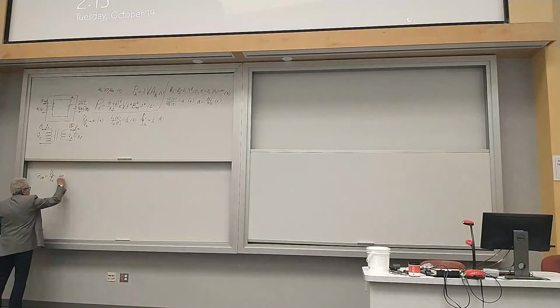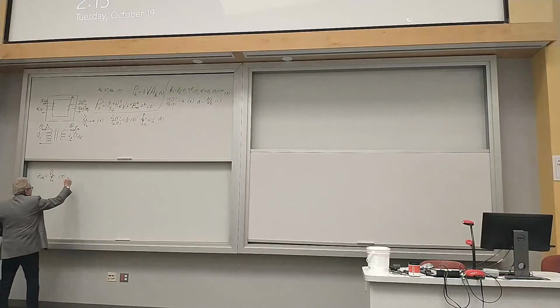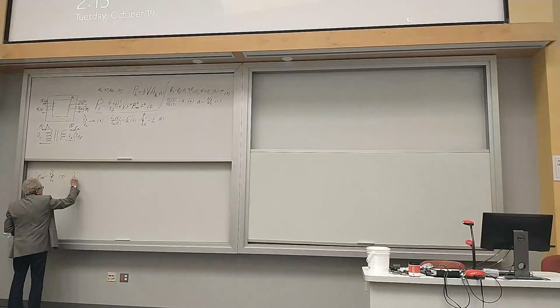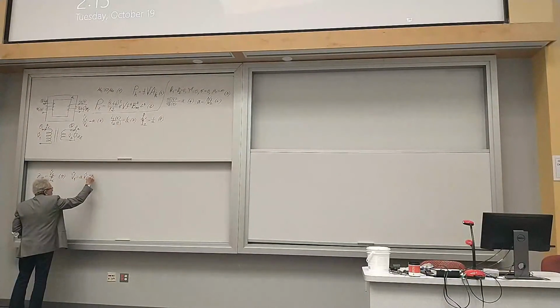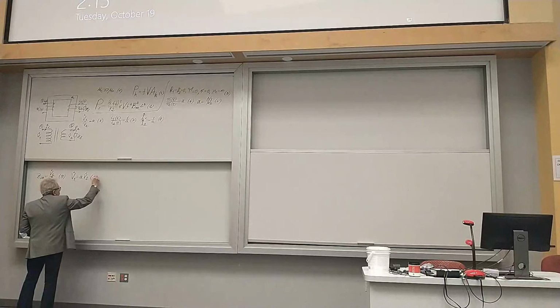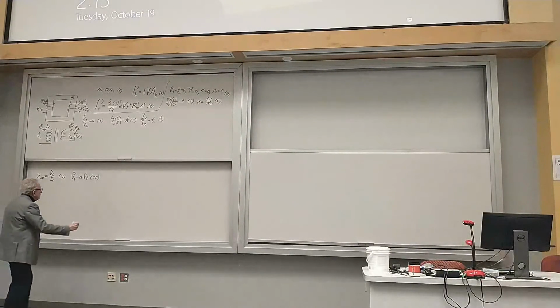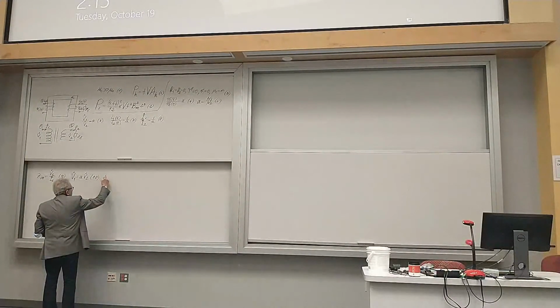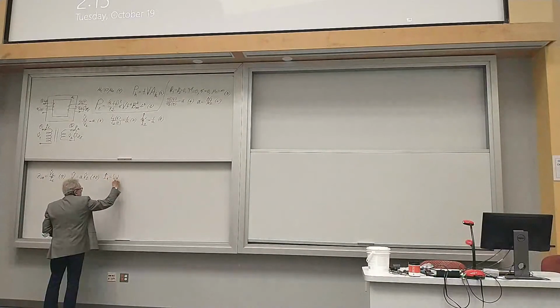In order to find this, I will use formula 6, and so I can write that V sub 1 is equal to A times V sub 2. Similarly, I will use formula 8 to replace I sub 1 by I sub 2. So from formula 8, I will find that I sub 1 will be equal to 1 over A times I sub 2.